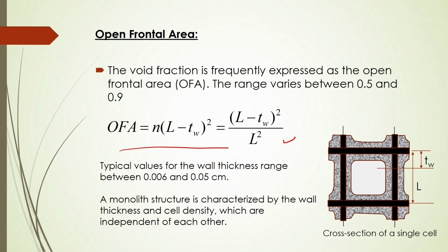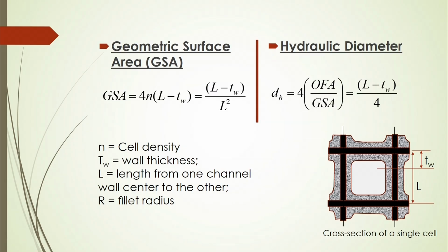So, that is why cell structure, cell density, and cell cross sectional area will be the geometrical effect for that particular chemical engineering process output. Now, geometric surface area is also important, because how you calculate that geometric surface area is actually responsible for the mass transfer between the surfaces.